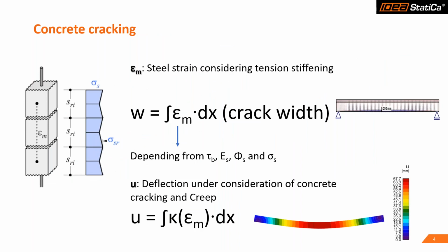Let's go now to the next important information. When we're talking about concrete, we also have to discuss the main issue, which is cracking. The program calculates numerically the strains in the rebars, and then it integrates the strains, so we get the crack width. So numerically, we calculate the crack width, and we can compare it with the limit value of our guidelines. If you have the strain values, also the curvature is known at different points along the beam.